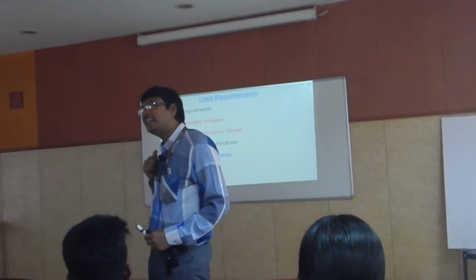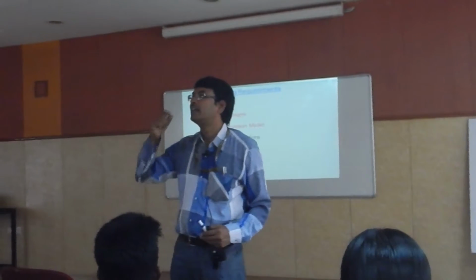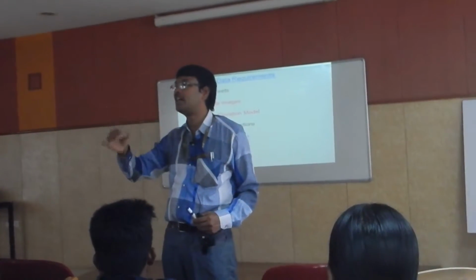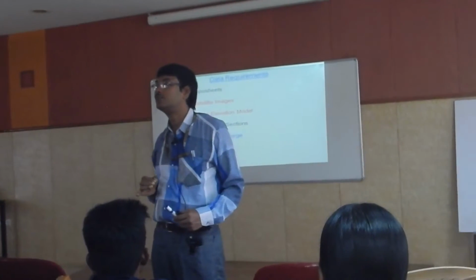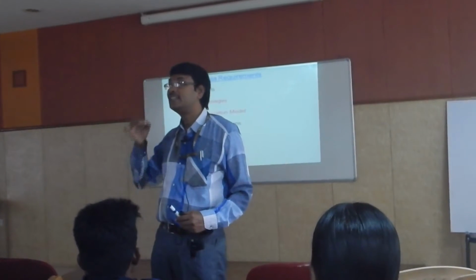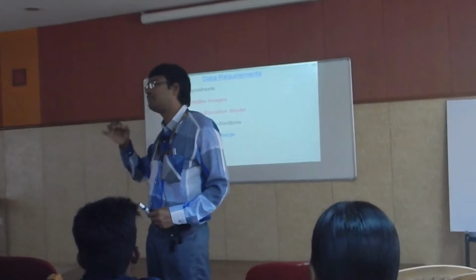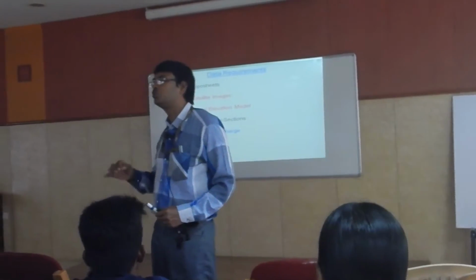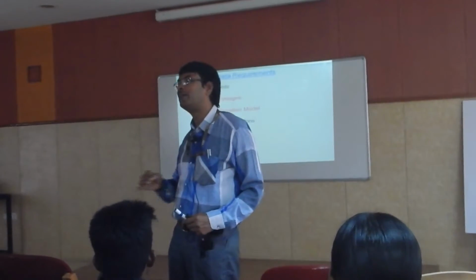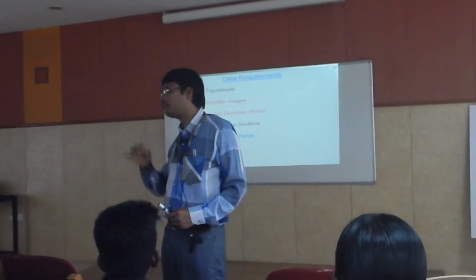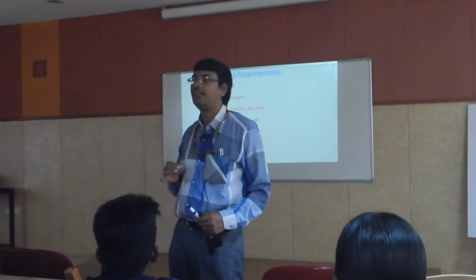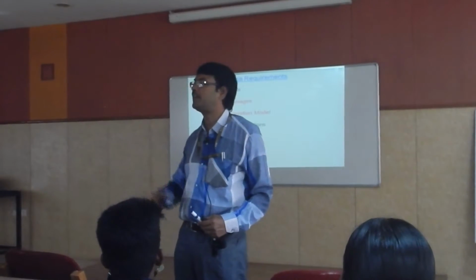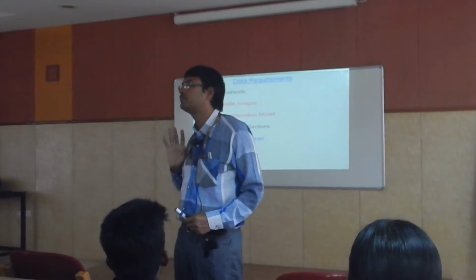That's why digital elevation models provide elevation values. That means every pixel has one elevation value. Due to this, the digital elevation model plays a very important role in water resources management: to do the reservoir analysis, the dam break analysis, the flood frequency analysis, the flood inundation mapping, and to identify the damage assessment. Definitely you require a good quality DEM.